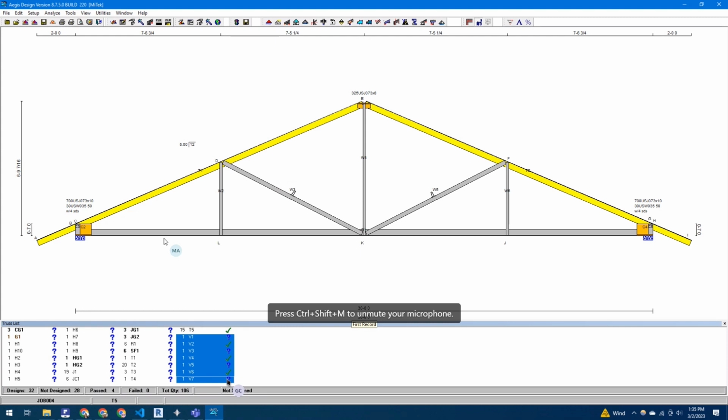Yeah, you can do that and then figure out how long it runs and divide by that to give you the pounds per lineal foot. If they all weighed 500 pounds between the three of them, and you got to run across a 20-foot span, you just divide them into it. That gives you a PLF. Yep. Apply it. So yeah, that'll work.